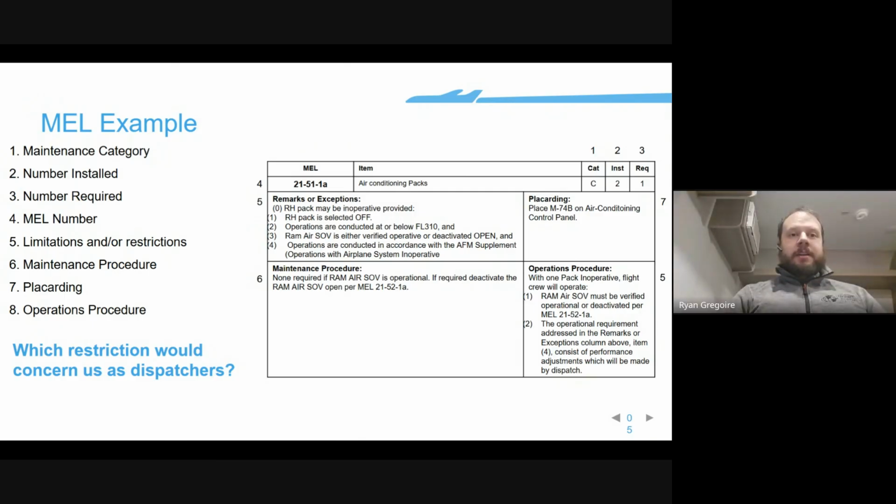All of these systems are rated to function by themselves, but obviously, as Jaden was saying, that does put a lot more strain on them. Just like our airplane can fly with only 1 engine, but that engine's going to have to do a lot of work and puts the aircraft at significant risk if it is operating by itself. Same thing with the AC packs. If we're putting that much pressure on a single pack, the likelihood of failure increases, and the wear and tear on the system increases, which makes it more likely to fail in the future, even once they get the remaining pack fixed, which reduces the safety margins and dispatch reliability of the aircraft. Thank you, Jaden.